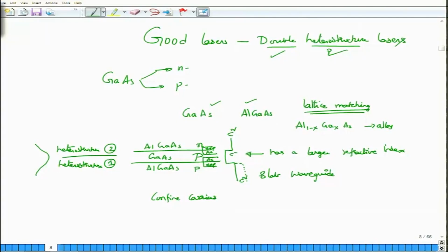Okay. What is interesting is that as the optical mode propagates through this active layer, it is actually seeing the accumulation layer. When we say accumulation layer, it means that more electrons are to be found in the conduction band, and similarly holes are to be found in the valence band in the central region. And because there is a large number of electrons, it is possible for us to employ this large number of electrons and corresponding holes to make them recombine, band to band recombination, so that they can give off nicely a large number of photons.